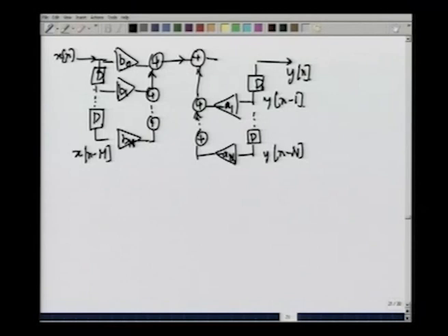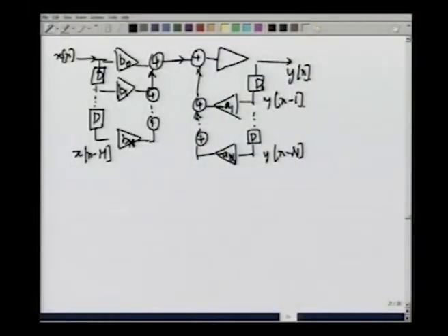So, in order to get all this to evaluate to y[n], you just now multiply by 1 by a0. So, what you have is 1 by a0 times a0 y[n], and that when connected to this will give you y[n]. This is a completely self consistent set of blocks which will generate y[n], the solution to the differential equation which had x[n] as the input.